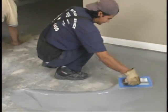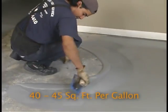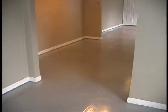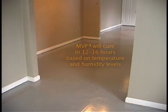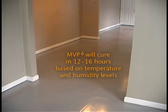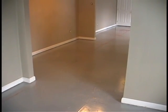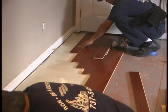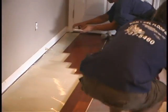As you apply the MVP4, you can expect to cover approximately 40 square feet per gallon when using the proper trowel. Continue your application of MVP4 until your entire substrate has been covered. The membrane will cure within 12 to 16 hours, depending upon the temperature and humidity level at your job site. The higher the temperature and humidity, the faster the cure. Once cured, you can move to the installation of your wood flooring.